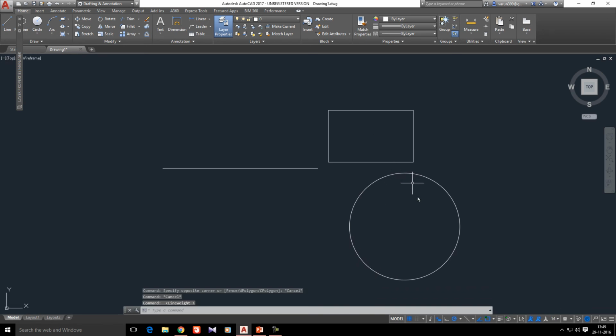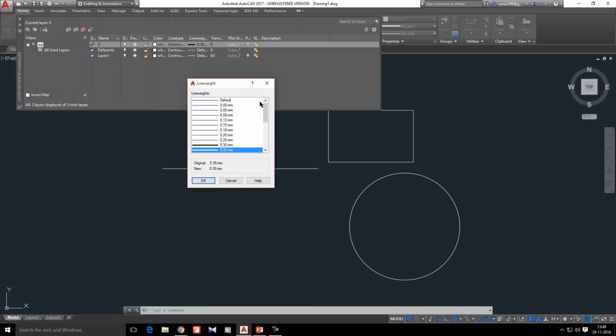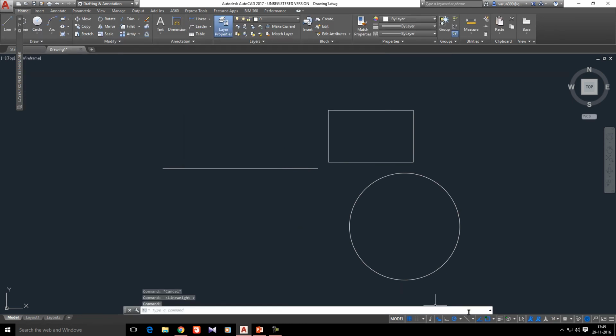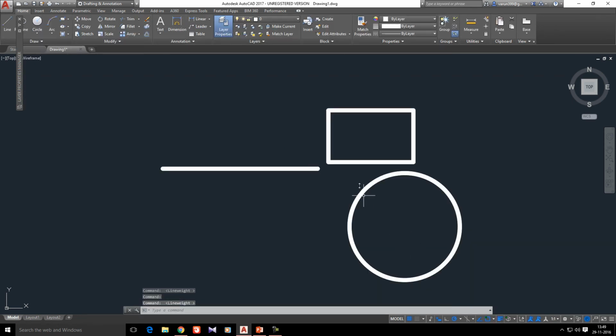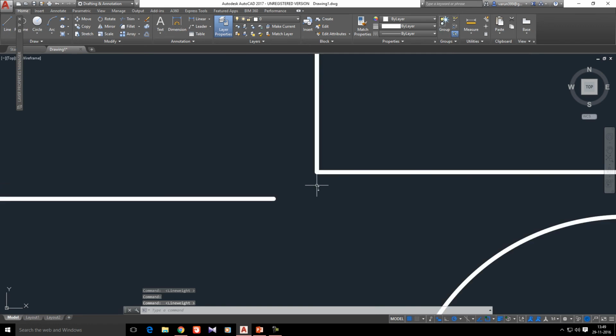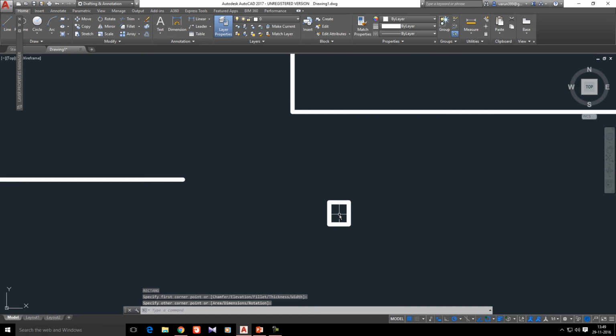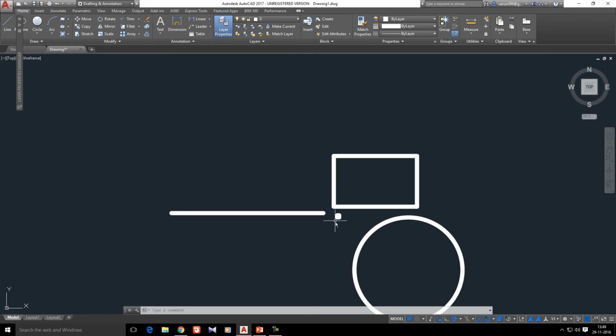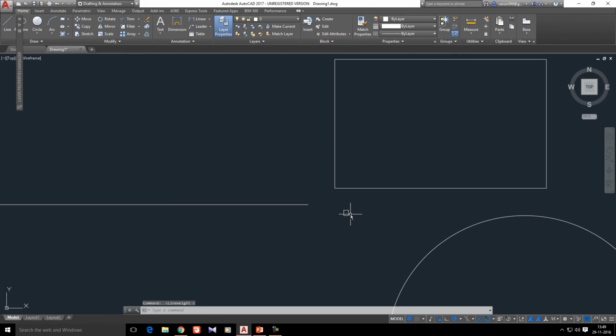So now you may be wondering why I should make this line weight display on and off simultaneously. Let me give you an example. Consider I change this line weight to some higher value like this and press OK and make this line weight display on. So now you can see it's a very huge rectangle. When you draw a small rectangle, it will be something like this. So you can see it's very difficult to find out what is there. It may be looking like a point. To make that distinction between that thickness and the structural shape, you can make this line weight off to see clearly that it's a rectangle.